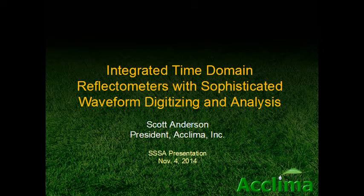In this presentation, I'm going to introduce you to an exciting new soil water content measuring technology. It's a fully integrated time domain reflectometer developed by Scott Anderson, the President and CEO of Acclima Incorporated. This new approach is a major breakthrough in TDR and is highly accurate, stable, and credible in making soil water content measurements. I will also show through theory and empirical data how it overcomes the errors caused by soil electrical conductivity, a major weakness in currently available non-TDR or non-TDT sensors.